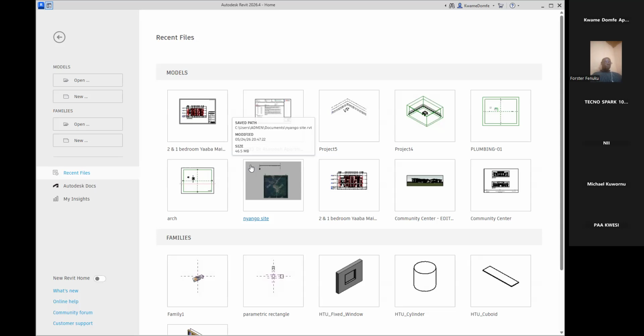When you finish drawing the WC, you convert it into a block and give that block a name, so that anytime you want a WC, you can go and pick that block and use it. So in the CAD environment, you were only drawing lines, then working with block libraries to do your composition. That was the two-dimensional. And if you want to print, you have to set up your papers, set up views, scale the views, and then put them on the sheets.